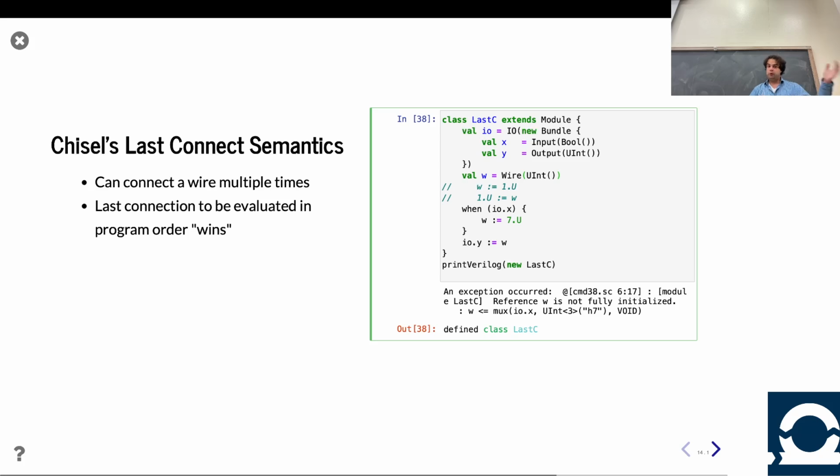So in a few weeks, we'll start talking about collections. There are collections that are immutable, like once a collection's made, you can't change what's in it. And there are other collections that are mutable. You can have a val point to a mutable collection and change the contents, which surprised some people, right? The point is the val itself is immutable, but the contents are mutable, right? And so with these chisel objects, under the hood, we can see in that diagram I drew, we're connecting inputs versus connecting outputs. That's changing the contents of these chisel objects. So even though we have a val pointing to these things, the chisel objects themselves internally have some mutation to them.